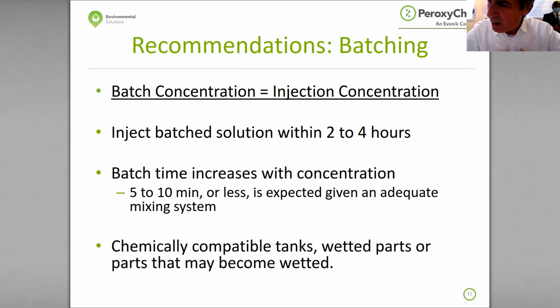You can use a single pump to pump whatever you batch into the ground because you no longer need to have dilution water, or you don't have to do inline mixing and blending of the different activators with sodium persulfate. One of the advantages now is that you can literally batch at your injection concentration. So if a design engineer is located in an office far away from the site, instructions can be relayed to the field workers indicating the preferred grams per liter mixture, and they would simply batch at that concentration.